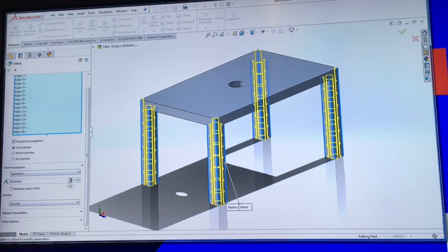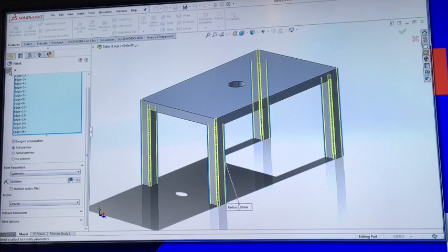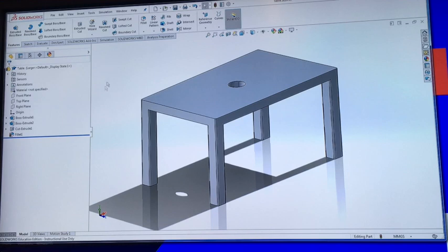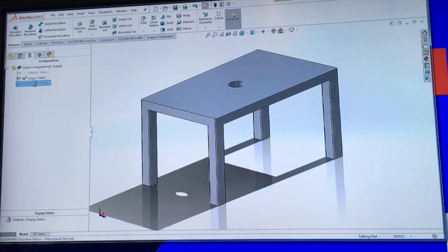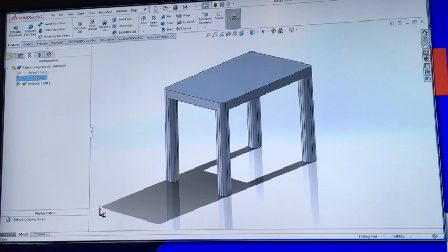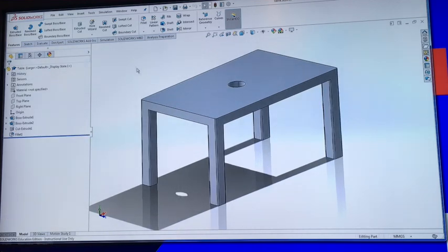So in this one here, under the fillet parameters with the size, there's the drop down here, I can link it to this configuration and change the size. Now if you see that traffic light symbol, that means rebuild. Have to hit the button up here, rebuild. So this enables you to have one part, and you might have a certain style to the thing that you've designed, but you can have multiple versions.